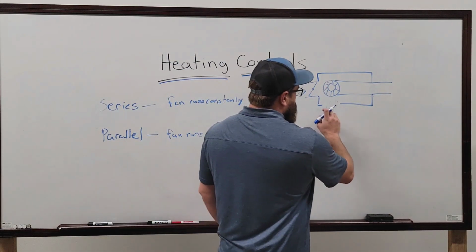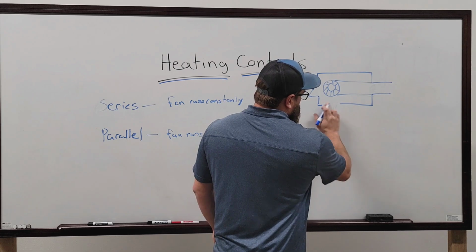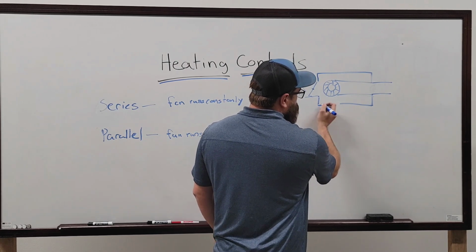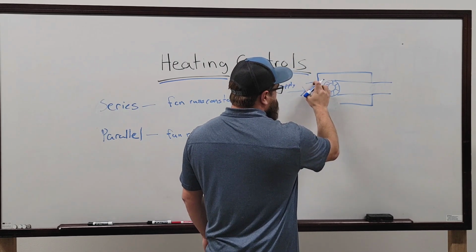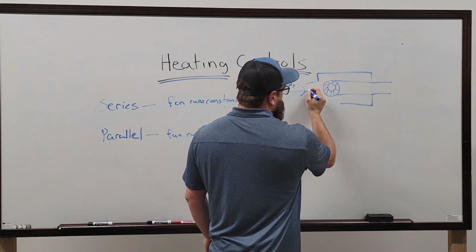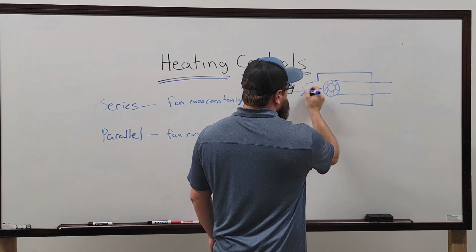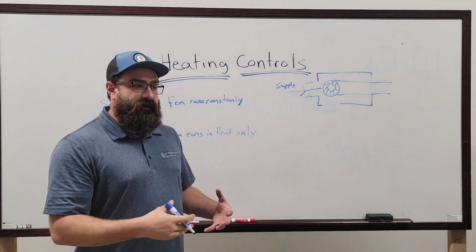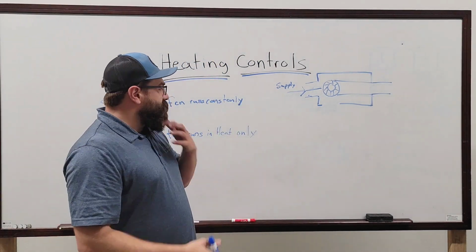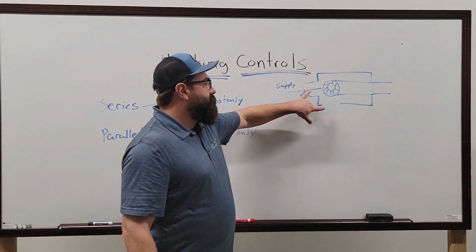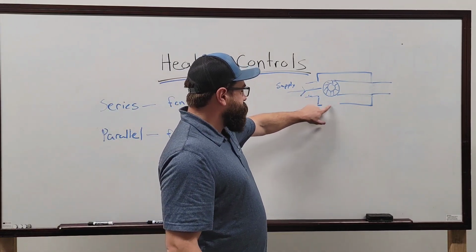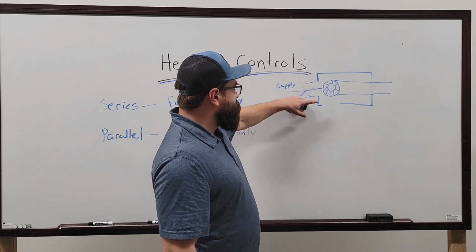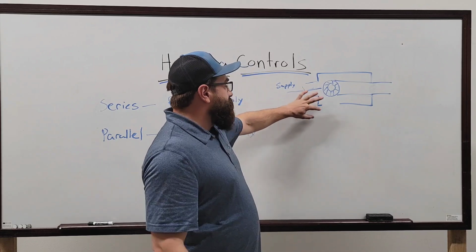Once this fan is running, this will go neutral when your damper is at its full control signal. Not necessarily full position, because boxes modulate airflow, not temperature. So what happens when they do an air balance on a job after we have installed controls is the test and balance guys come through.